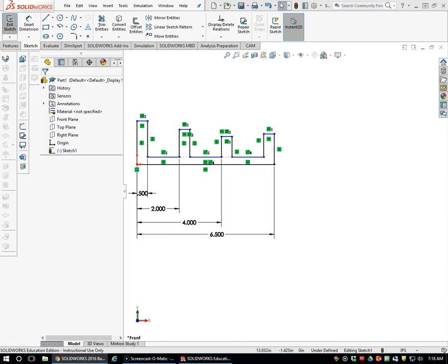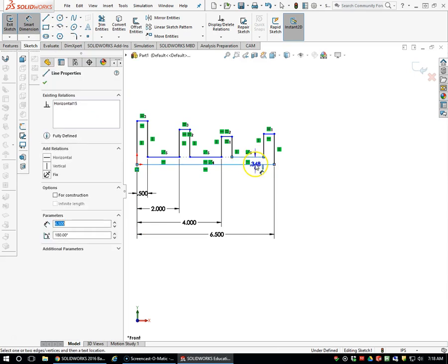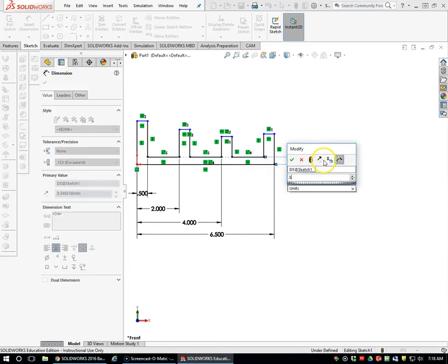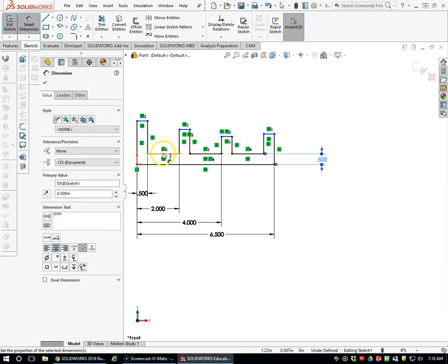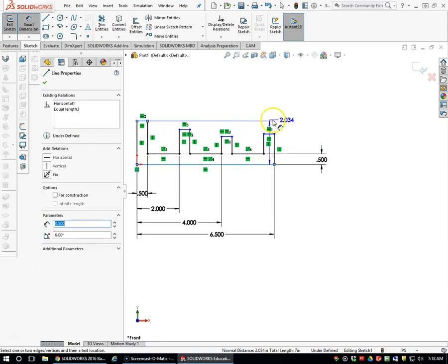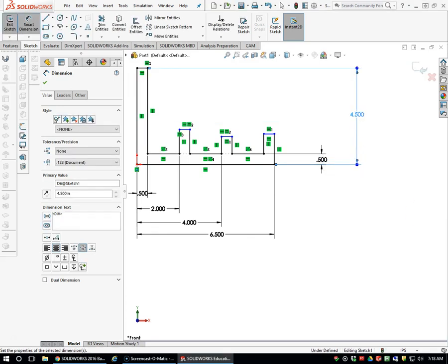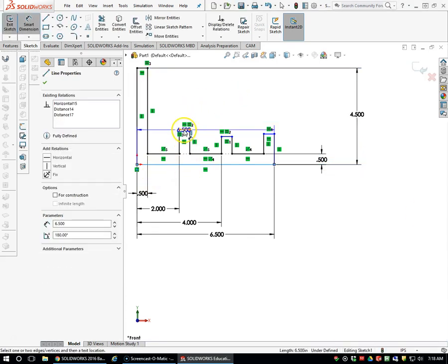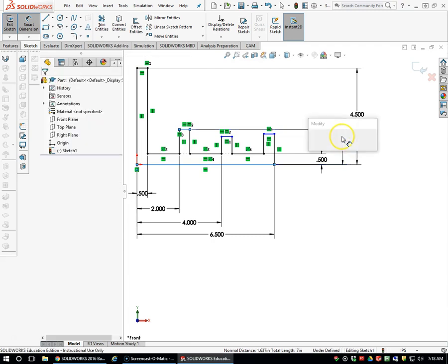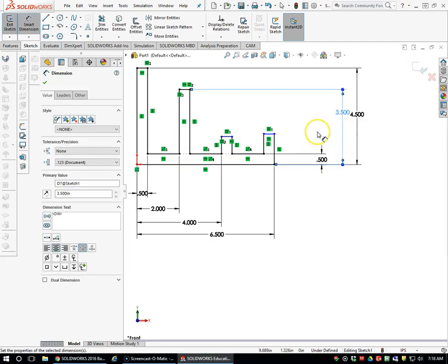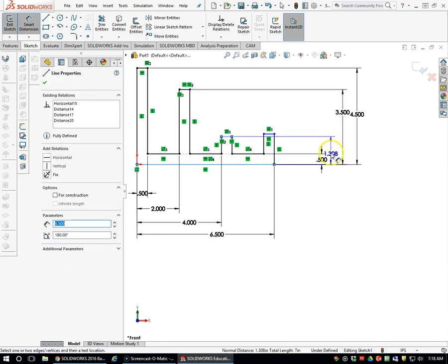So I'm on page 3-11. I'm going to go back to my dimension tool and start adding these pieces in. Now when I put this first dimension in of a 1/2 inch for the height, notice it moved all 3 lines because we had that collinear relationship. I'm now going to select the bottom line and the top line and go ahead and add these in. Just follow along, add each of these dimensions in.